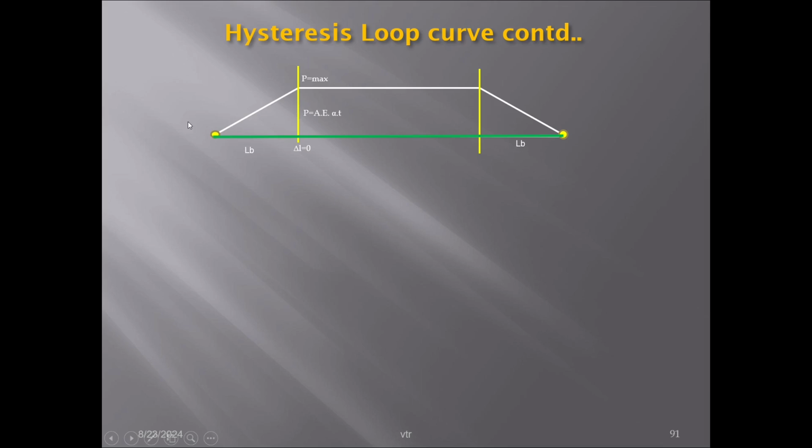To accommodate the expansion and contraction, we provide switch expansion joints at the ends. As already discussed, the gaps at the SEJs are to be inspected and checked periodically. Being an indicator, the gap will tell you about the performance of the LWR, whether it is working properly or not.